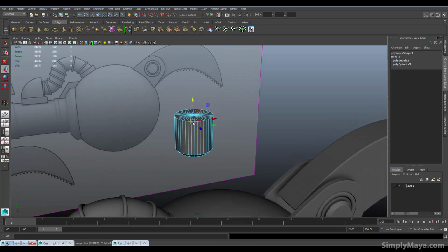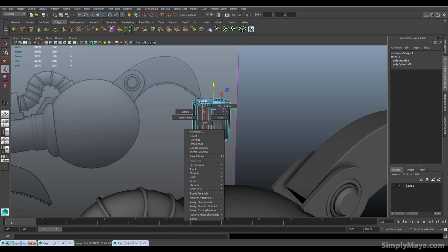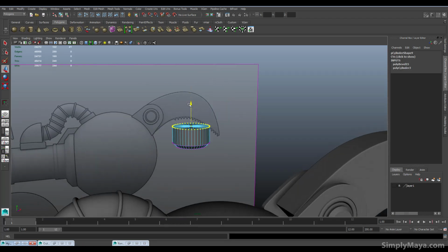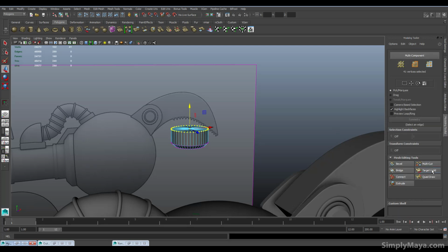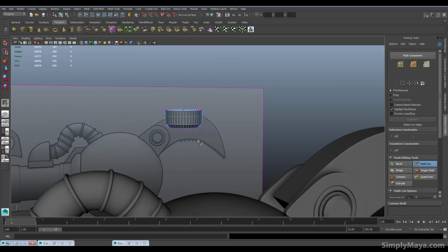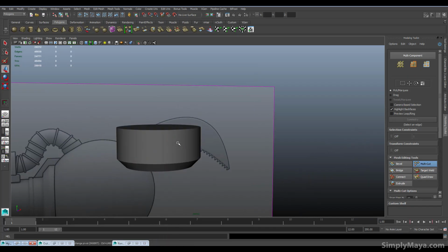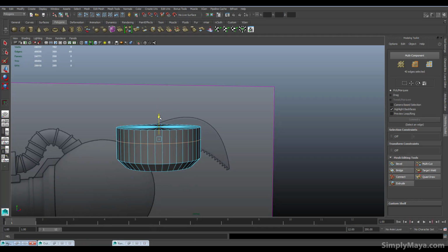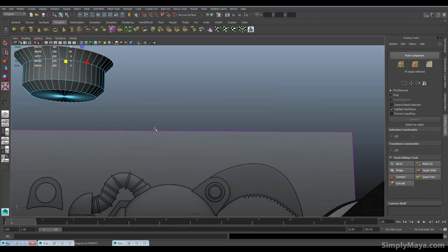And then for this top edge, I actually can't put a bevel on it. I want a reverse bevel, and you'll see why in a second. It's easier if I just build it, demonstrate it, and I think it will be easier to see that way. So I'm going to do a reverse bevel here, or reverse chamfer in this case, for which I need to put an edge loop at about the same distance as the bottom one, so that might be a bit too much. I'll just slide that up. Then I'm going to select this surface and just scale it up to create a reverse bevel.